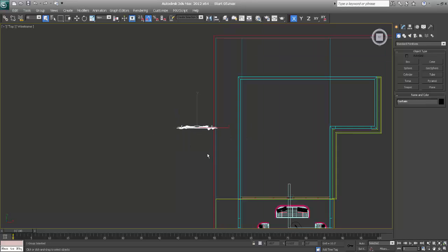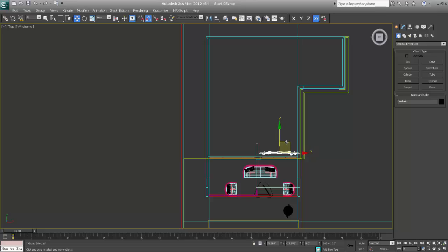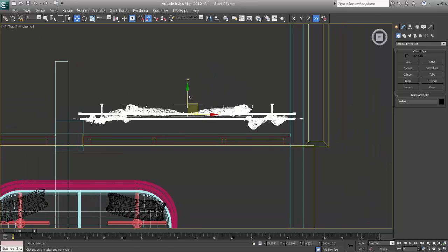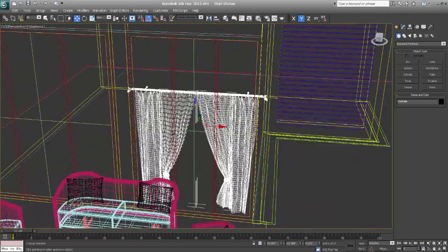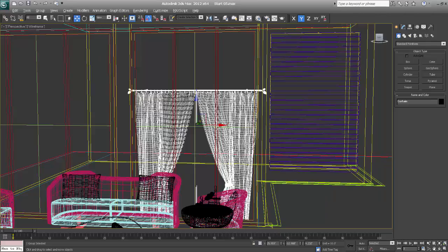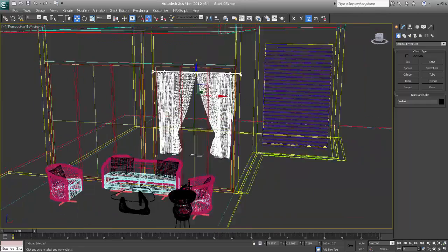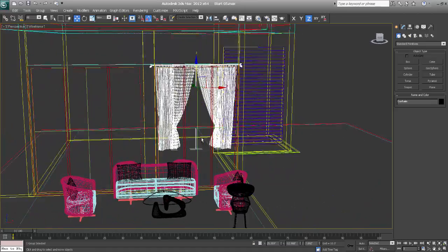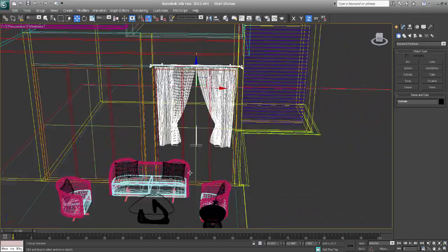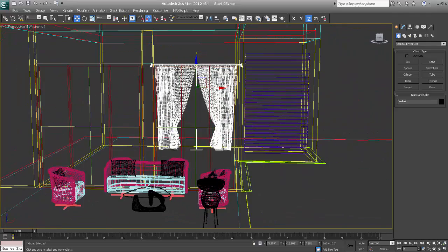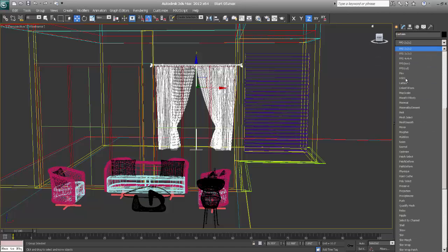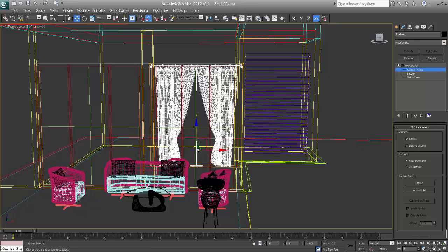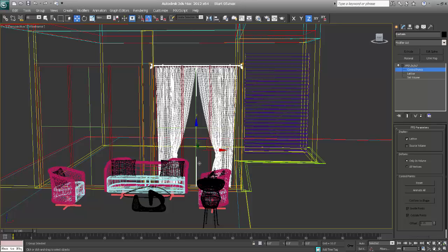This box I want. So I'll add edit poly. Actually the fitting is over here, but there is absolutely no need to move, because we only want to show the curtain part, and the best way is to make a simple box. It will be easier. Snap, and the challenge will be that the height should be till here. Just I'll go and say FFD, and this is done.